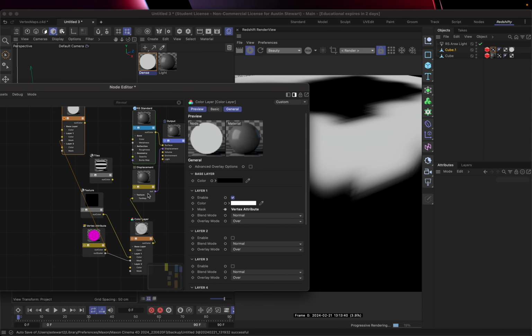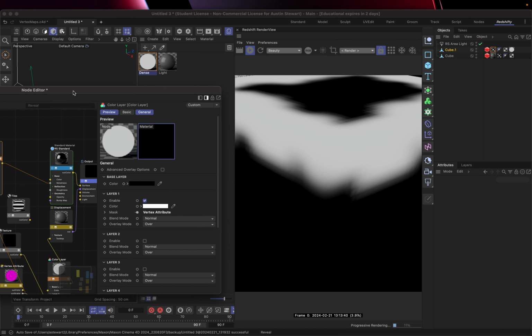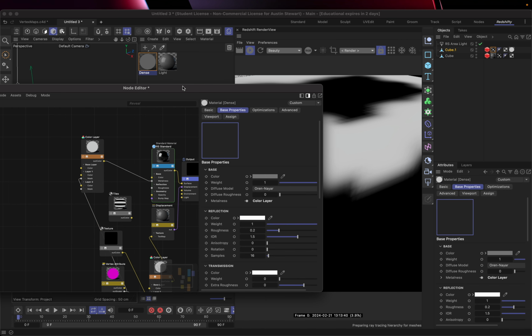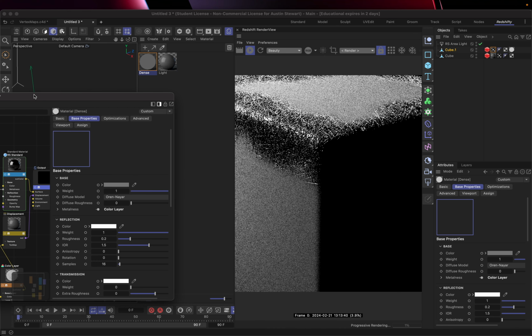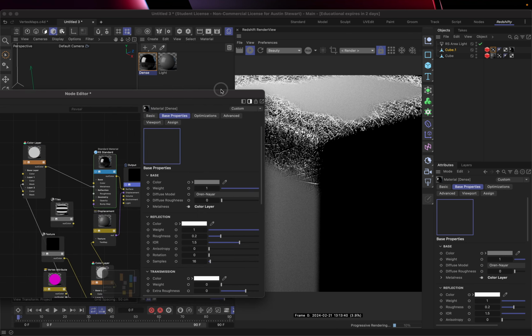And now we could set this to our metalness value over here. So I'm going to come over and say metalness. And then I'm going to undo solo mode so that this will update. Right, so now I've got it set so it looks like it's metallic on the edges and it's this gray material on the planes.